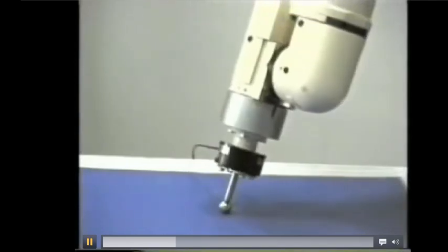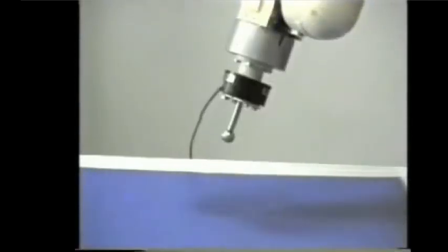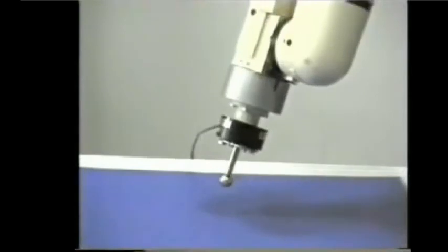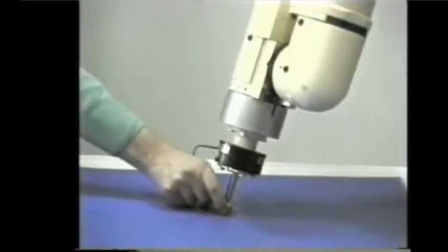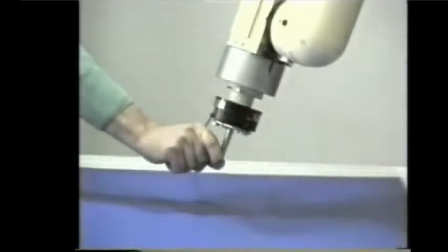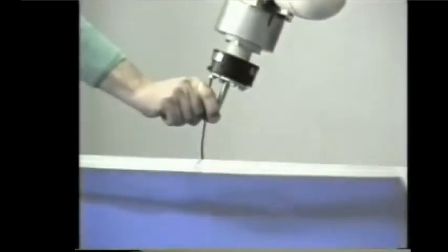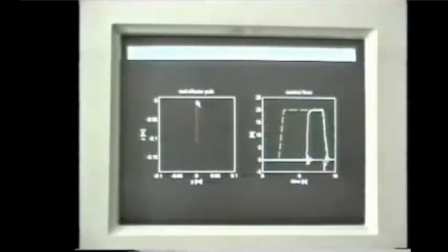So you get approach, and then you will push enough until you reach the desired position. Of course, when you reach this desired position, you release the controller, you move the robot away using force control. And here you see the resulting track. In free motion, you're getting straight on the vertical until you touch the environment, and at that time, your reference of force will get to the desired one.